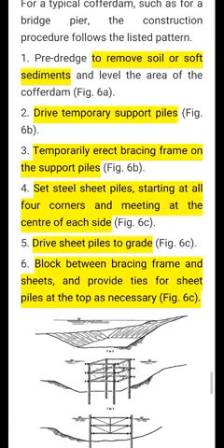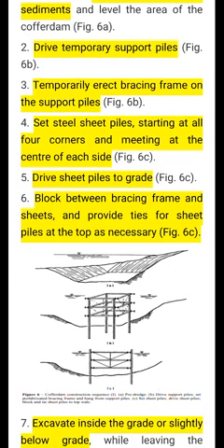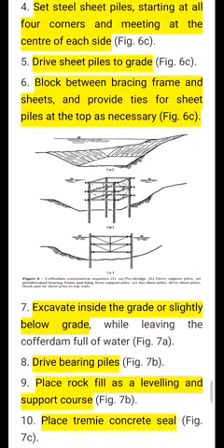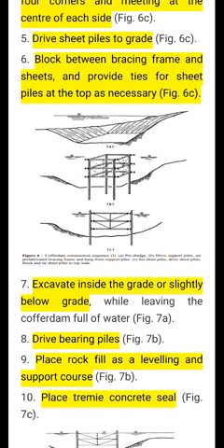Fifth step will be to drive the sheet piles to grade. Driving means insertion of the sheet piles. Sixth step will be to block between bracing frames and sheets and provide ties for sheet piles at the top as necessary. Bracing is required from top to bottom wherever needed to avoid deformation.